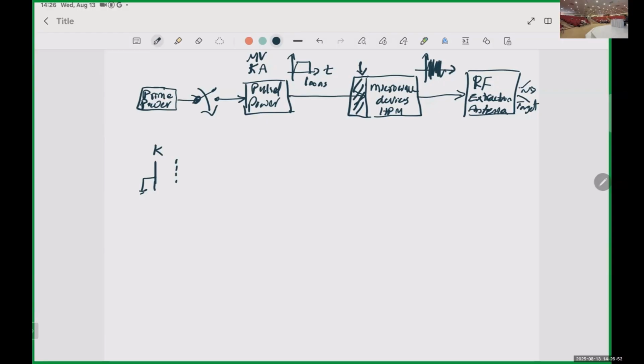The arcing is going to prevent you from having any good electron emission. Now, if the electric field is this way, then of course the electrons will come here, and some of them are going to hit this grid, and some of them are going to fly through. And if there is nothing, they want to come back toward your ground here. But for our case, since we are integrating this with the microwave source, we force them to follow a static magnetic field, B.